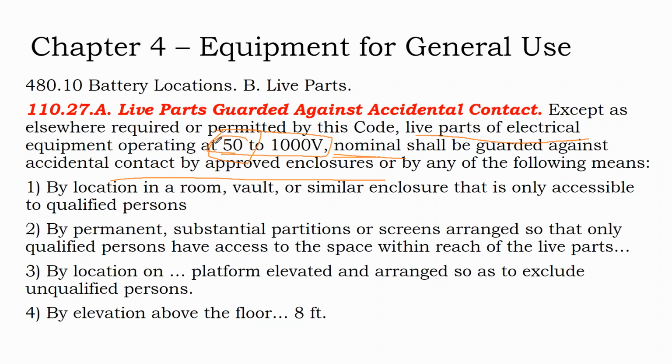And that's why you need to take this shed and make sure that the door has a lock on it, because you don't want unqualified people coming into that room. And he wasn't very happy about that because he wanted to keep yard equipment and stuff inside the box and didn't want to keep his battery room locked. And it's like, well, that's a fundamental part of a battery enclosure area, to have it be secure from the outside.